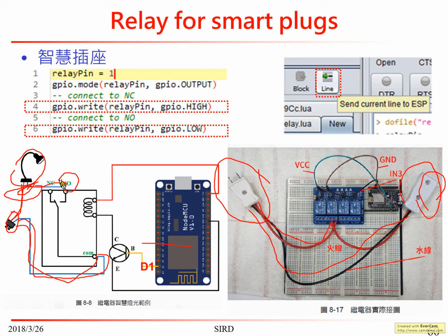So if you detect that the light is too dark, then you switch this to become 1, and it will emit the LED light. It will change the coil, and it will flip this iron to this way, so that they become connected. Okay, so you can just use high and low to turn the light on or off.